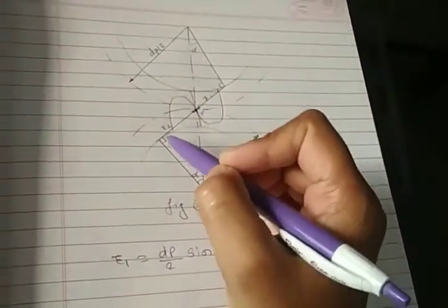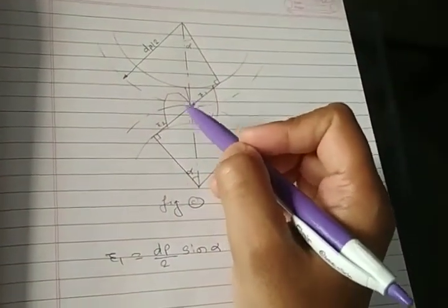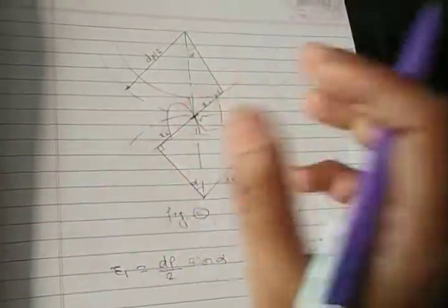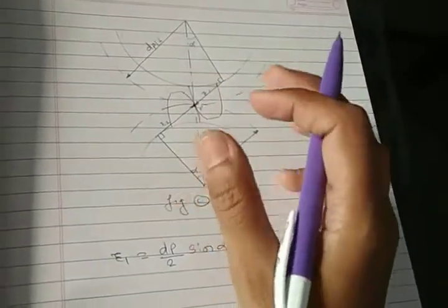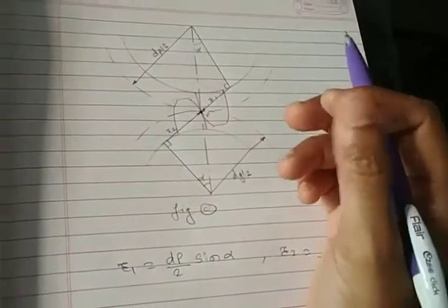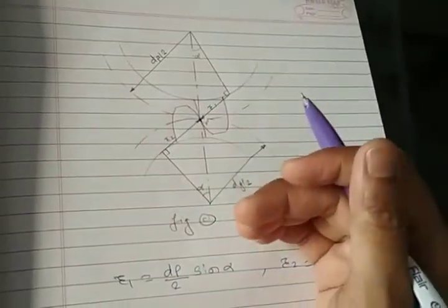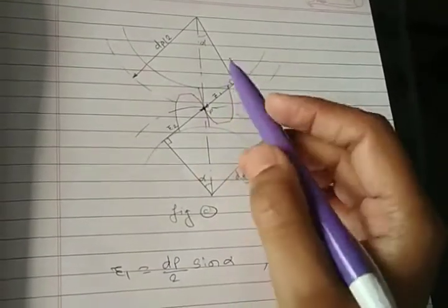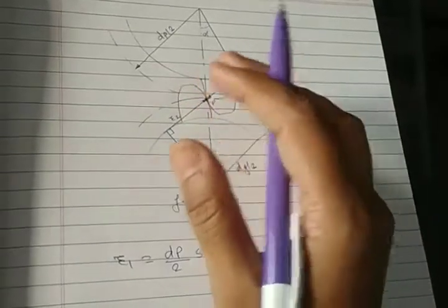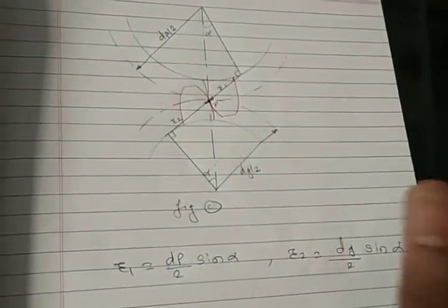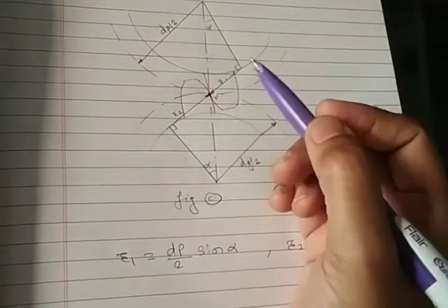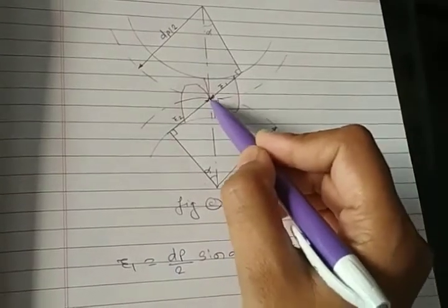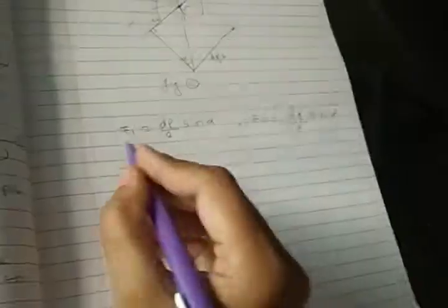Now we consider these radii of curvature at the pitch point. There are two reasons behind that. First, the wear of teeth generally occurs near the pitch line. And when only one pair of gear teeth carries the entire load, the point of contact occurs at the pitch point, and when contact takes place at the top or at the bottom of the tooth, usually two pairs of teeth are in contact, and the two pairs share the load. So when we consider one pair sharing the load, the point of contact is at the pitch point.